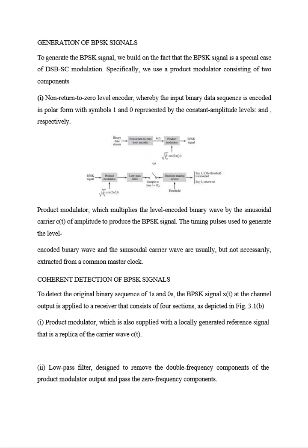Symbol 1 is generated by one particular phase of the signal, and symbol 0 by another phase, so both are shifted by 180 degrees. These BPSK signals are represented as antipodal signals because they are uniform in amplitude and frequency. The only difference is that they are phase shifted by 180 degrees. Such signals are called antipodal signals.